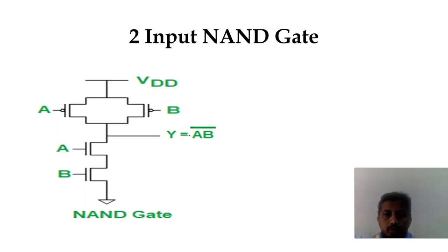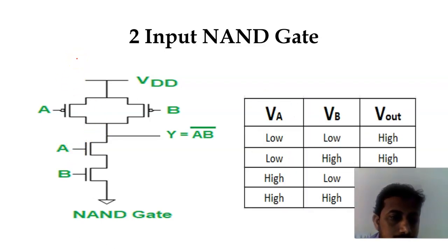Now we'll go for the two input AND gate, NAND gate, sorry. The two input NAND gate expression would be given as what? The expression is A dot B whole prime. So what is it? AND invert. When you go for AND, NMOS should be connected in what? Series. PMOS should be connected in what? Parallel. So here it is with parallel. We will see whether it follows that, whether you are getting the output correctly or not.